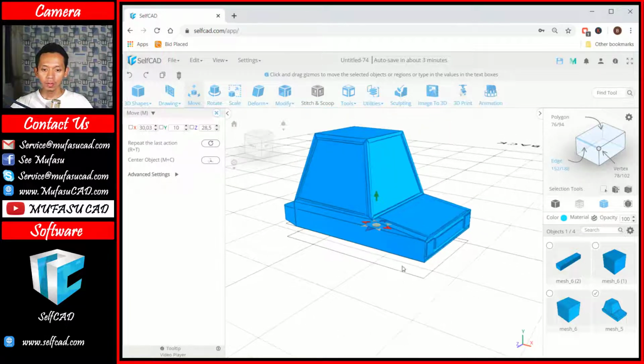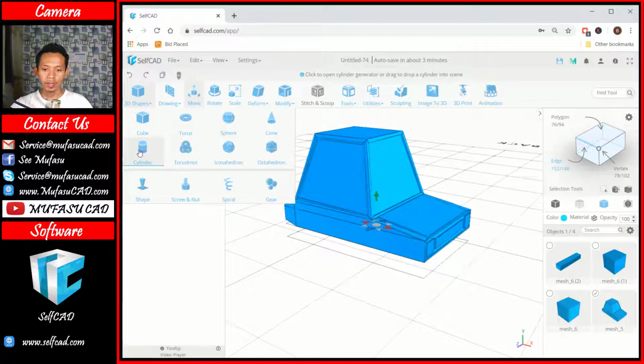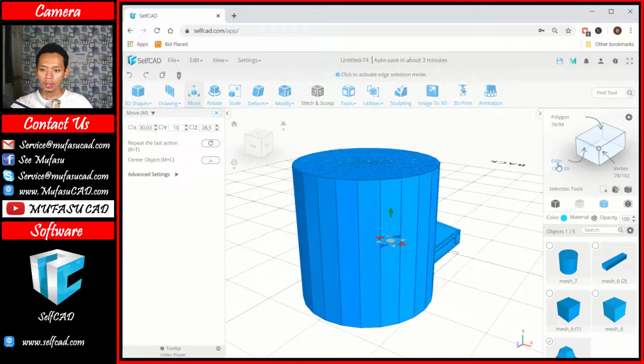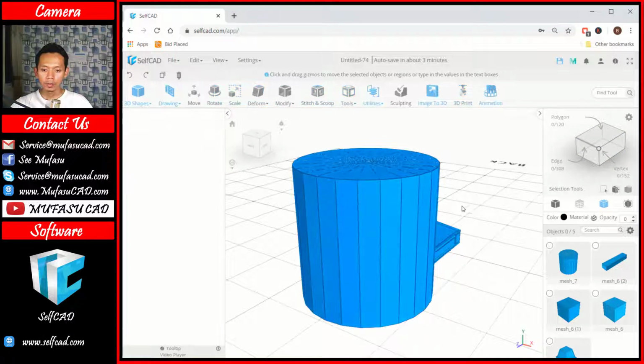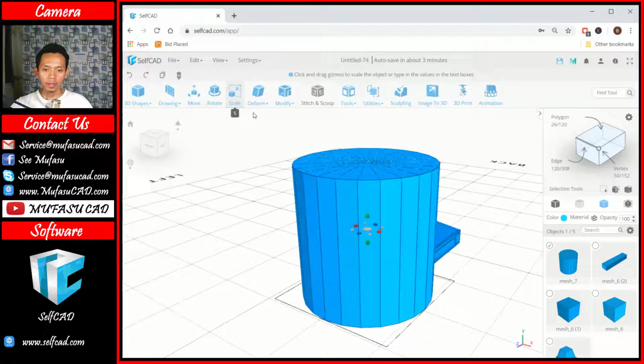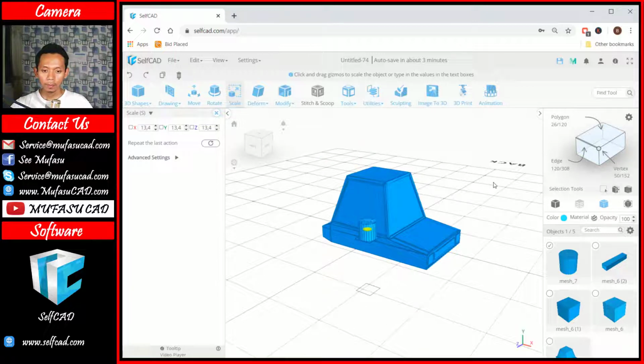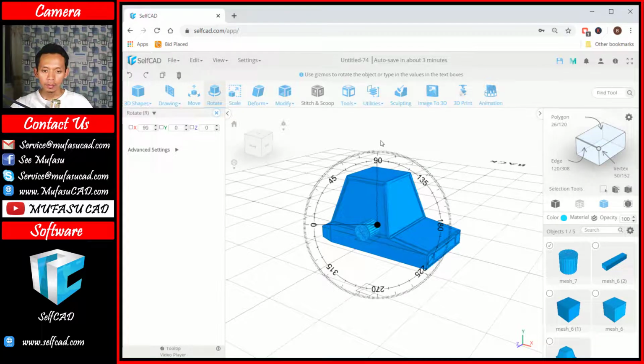now to create the tire, we can use this cylinder option. You can attach into here, and next I will uncheck this edge option. We select this cylinder object, and then you can use scale. Okay, I will scale, make it smaller, and then next we can use the rotate option to rotate in the right axis, okay, by 90 degrees.